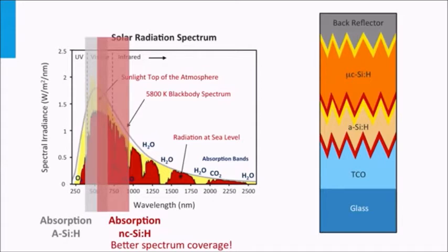First, the amorphous junction has the highest band gap of both materials and will act as top cell. The top cell is the PIN junction that is facing to the front and where the incident light is passing first. The cell with the highest band gap acts like the top cell, as the spectral part with the most energetic photons has the smallest penetration depth in materials. The bottom cell is the cell with the lowest band gap. This cell has to harvest the photons from spectral parts with the lower energetic photons.